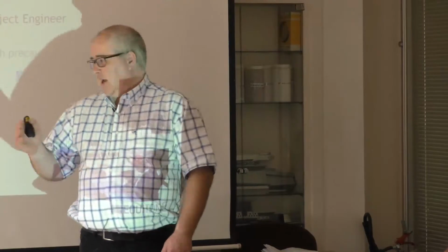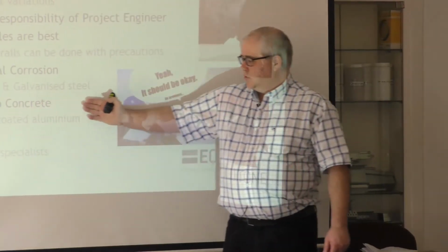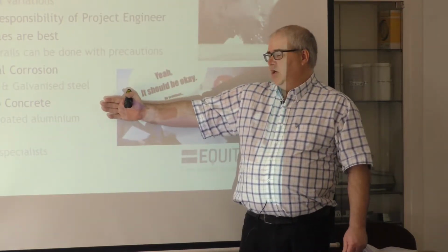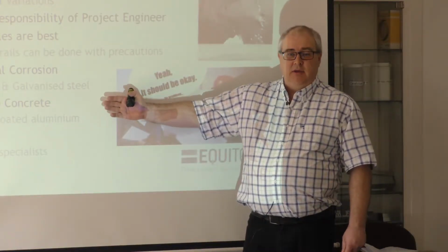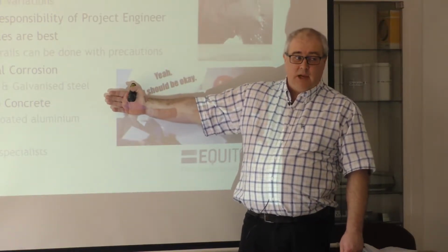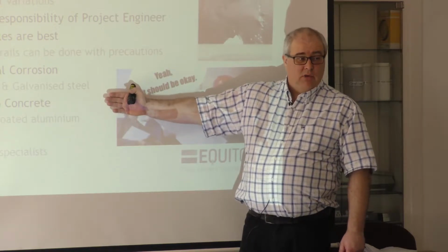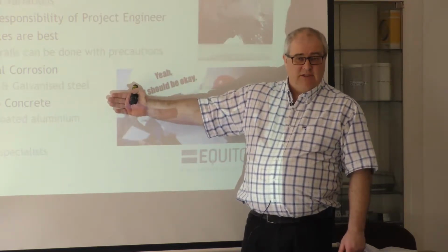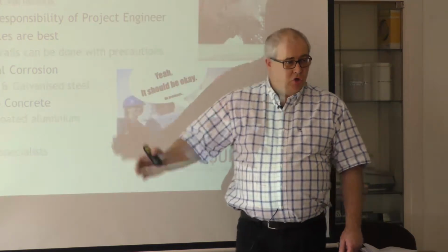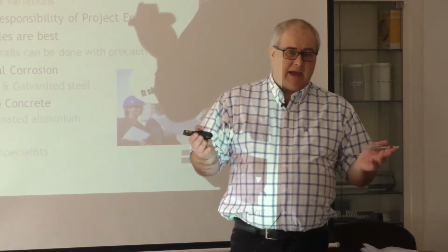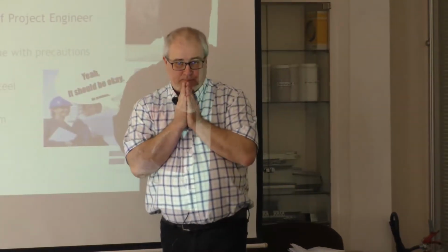So, in practice, what I'm leaving up to you is that if you do have an engineer or an architect that has some knowledge of this, maybe they've worked in the USA or in Europe sometime, it may become an issue on a job site when you're fixing your framing system. Okay? In Europe, we normally get over it by using these thermal pads. Normally in structural aluminium framing systems they might put a little bit of bitumen tape or bitumen paint behind the aluminium, or just paint the back of the bracket. You just want to stop that direct connection between the two.